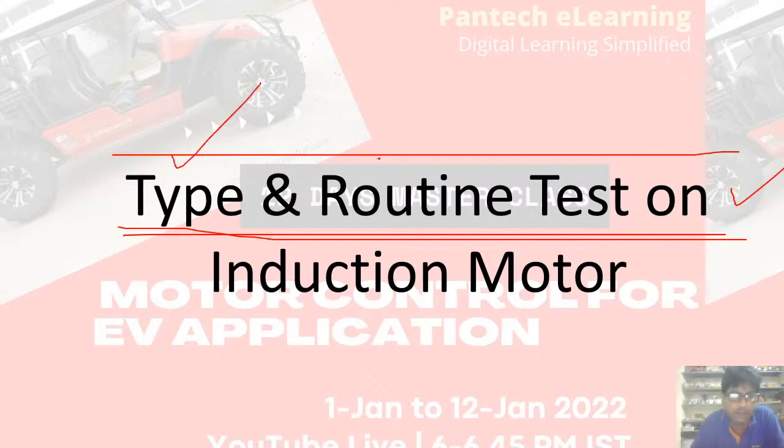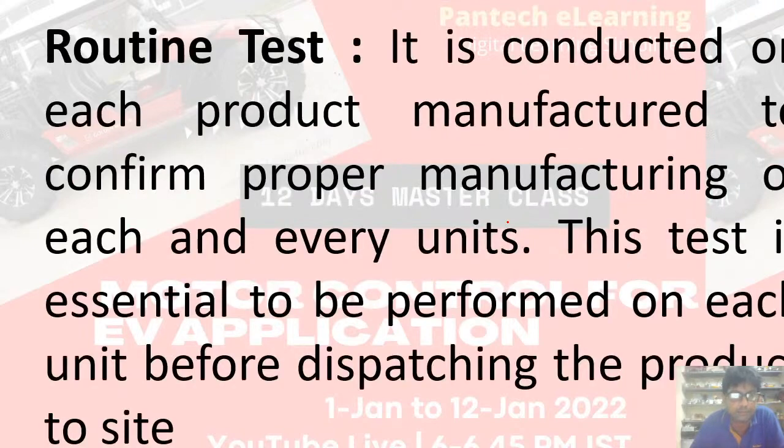They are mainly classified into routine and type tests. So what is a routine test? Say I have given a bulk order of 100 BLDC machines or 100 induction machines. These tests will be conducted on each product. That means on the 100 machines, I have to perform these tests.